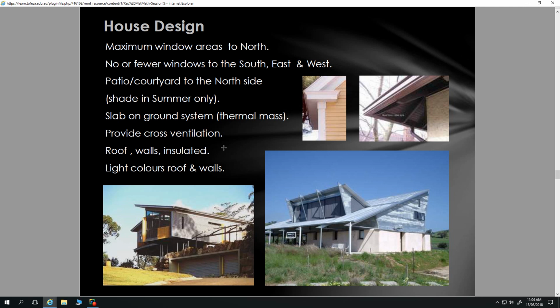Roof and walls, and I'll also add to that floors, insulated. That does play into the design. It plays into the design in determining how much space you have provided for insulation in your roof and walls and floor, whether you can get a high R value of bats. But there are other ways around that. They cost money, to have an insulation with a higher R value that has less thickness, but they're typically much more expensive.